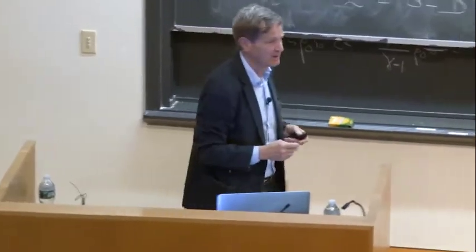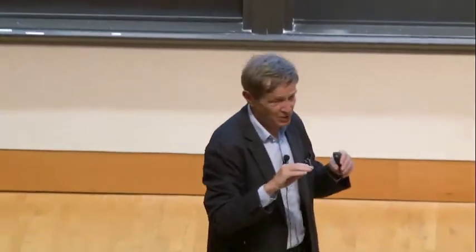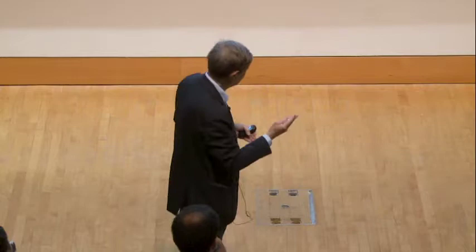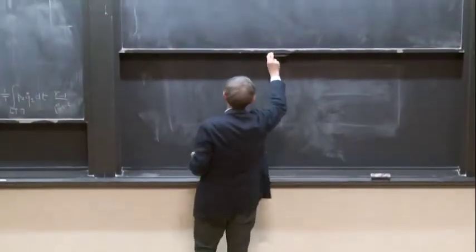Yes? You mentioned you could measure the transfer function. How do you do that? You can measure the transfer function. So how is it done in practice? The velocity can be measured using laser Doppler velocimetry or a hot wire, or sometimes, for example, in a typical configuration.